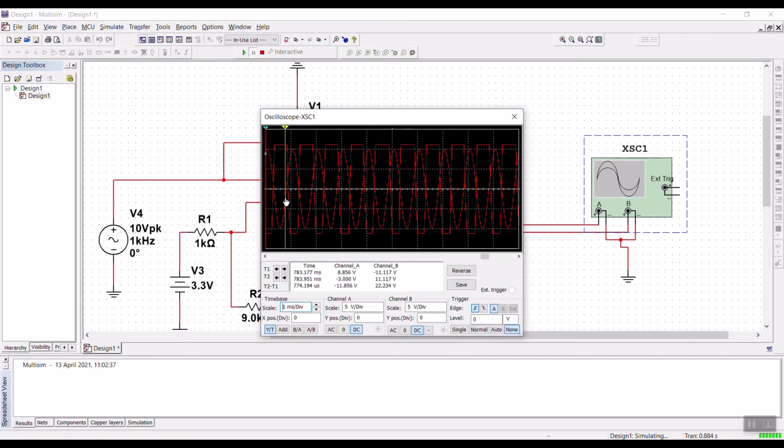The end where the capacitor waveform crosses the rectangular waveform upwards will be considered the UTP, and the other one the LTP. Just drag it. In channel A you have to get 4 volts and 2 volts. So just drag it wherever you get it. Approximately is also fine. So we've got it. The upper one will be the UTP, the lower one will be the LTP.